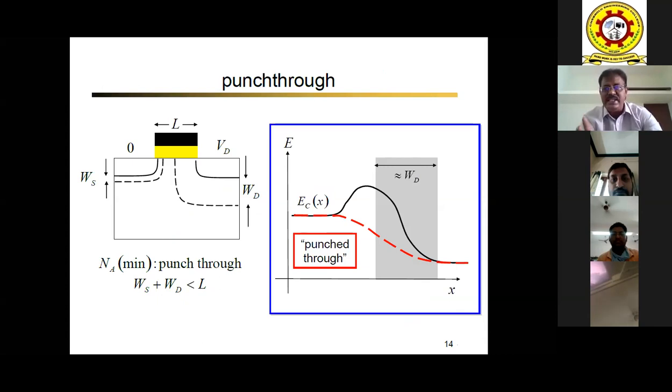Now, since the length of the gate was larger earlier, even though there was a VGS, it was not affecting any carrier movement from source to the drain. Now, since the length of the gate is reduced and it's becoming a short channel, the impact of this gate voltage on the movement of the carriers also comes into consideration. Now they get surface scattering. What happens is, with excess positive voltage at the gate, your electrons are getting attracted, and instead of moving straight from source to the drain, they collide with the surface of the SiO2 interface. So we call this phenomenon surface scattering.